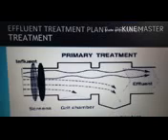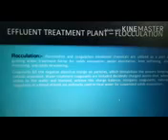Coming to flocculation, flocculation and coagulation treatment chemicals are used in raw water treatment processes or effluent water treatment processes for solids removal, water clarification, lime softening, sludge thickening and solids dewatering.